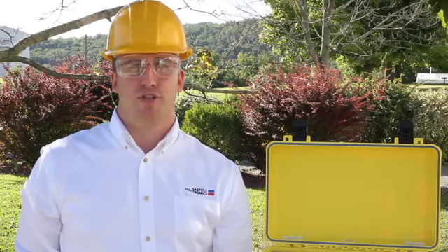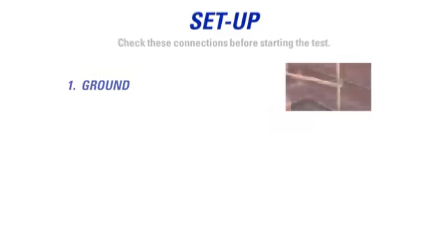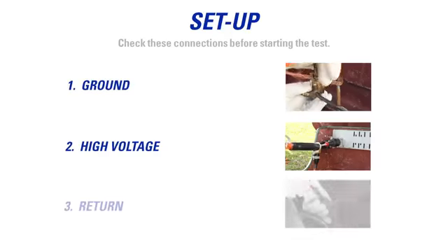If you have not operated the 5250 in basic mode, I recommend following the link below to our 5250 basic mode demonstration. Before initiating any test, make sure to check your connections to the ground, high voltage, and return leads.